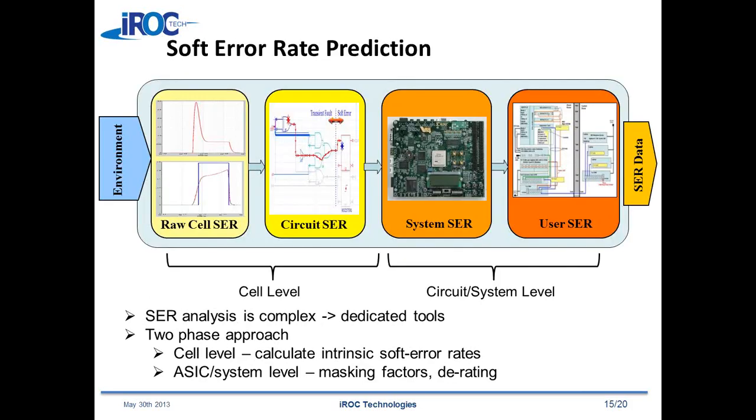Right. Well, it's important to include soft error analysis into the design flow up front, and there are two parts to that. The first part, and it's very important, is soft error rate prediction. Predicting the effective or the visible soft error rate of a complex chip is not an easy task. You need to consider it at the cell level, to understand, given the particle flux that's present in a terrestrial application, at what rate am I going to see upsets in my flip-flops? At what rate am I going to see glitches in my gates?